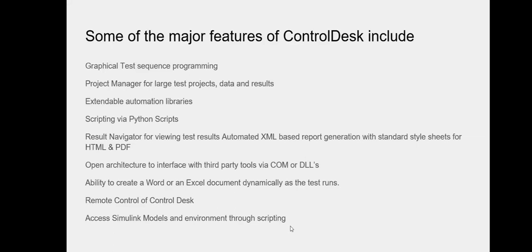All those are the ECU environment, ECU inputs and outputs. Those things we can access through script, right? We can access the plant model, all the digital IOs and analog IOs, everything through this control desk.